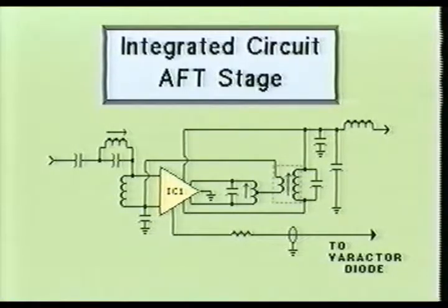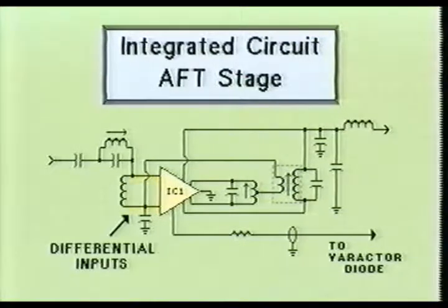Integrated circuits are also used in automatic fine-tuning sections. Here you see an integrated circuit which completely replaces the Foster-Seeley discriminator and the common emitter amplifier circuit. This integrated circuit not only provides error detection through its two differential inputs, but it also provides proper amplification of the error voltage to the varactor diodes.